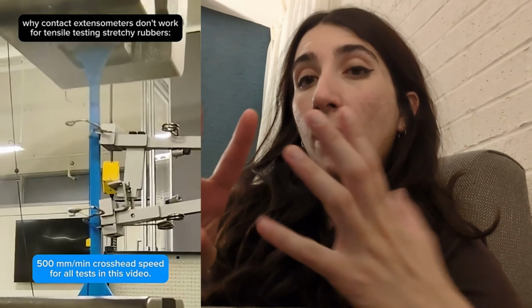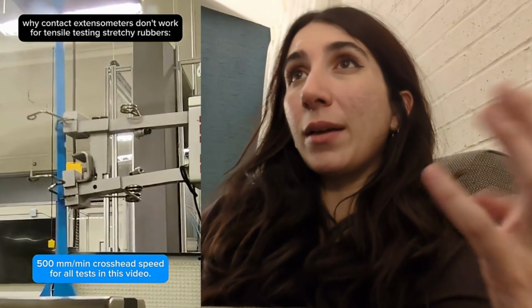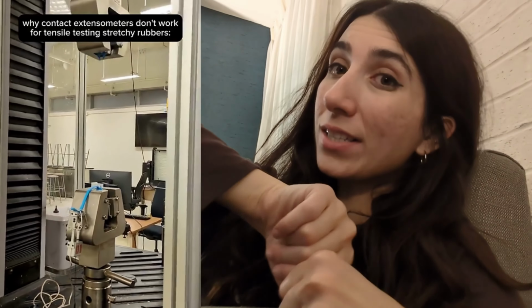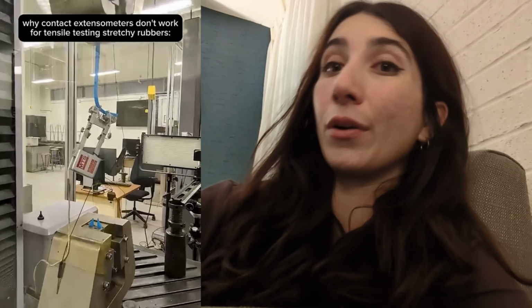Usually contact extensometers are used for materials that are not going to stretch as much in comparison to video extensometry, which would be more ideal for your rubbers, polyurethanes, very high strains, able to stretch upwards of 200 or 300% of their original gauge length. Without an extensometer on the specimen itself, you're essentially measuring the movement of your entire testing machine, not just the material. So you can't really see the real story of how that specific piece of material is actually deforming or stretching.